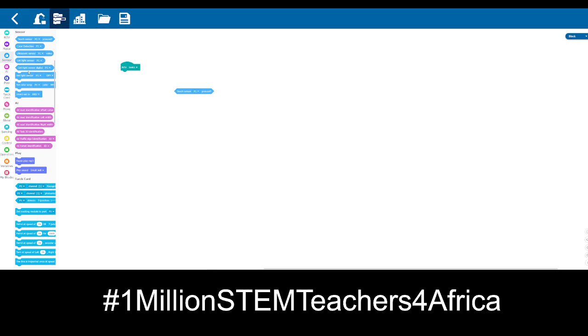Using that principle, you can either get Boolean values, that is 0 and 1, or you can get an analog value, a wide range that you can use to determine if more light has been absorbed or more light has been reflected. Based on that, you can say that this surface is black or this surface is white. We'll be using this a lot when we're doing line following. In our next class, we'll be doing a lot of line following.